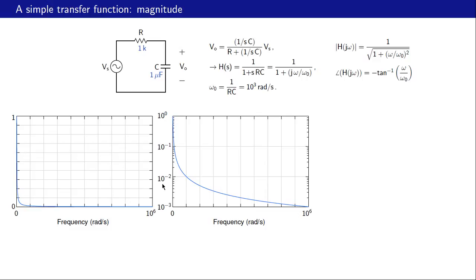For example, let us take omega equal to 2 times 10 raised to 5 radians per second, that is here. And now we can read the value of mod of h from this curve. So somewhere there. What is that value? So this is 2 times 10 raised to minus 3, 3, 4, and let's say 5. So something like 5 times 10 raised to minus 3. This was not possible to do in this older plot because the y scale had also got compressed here.